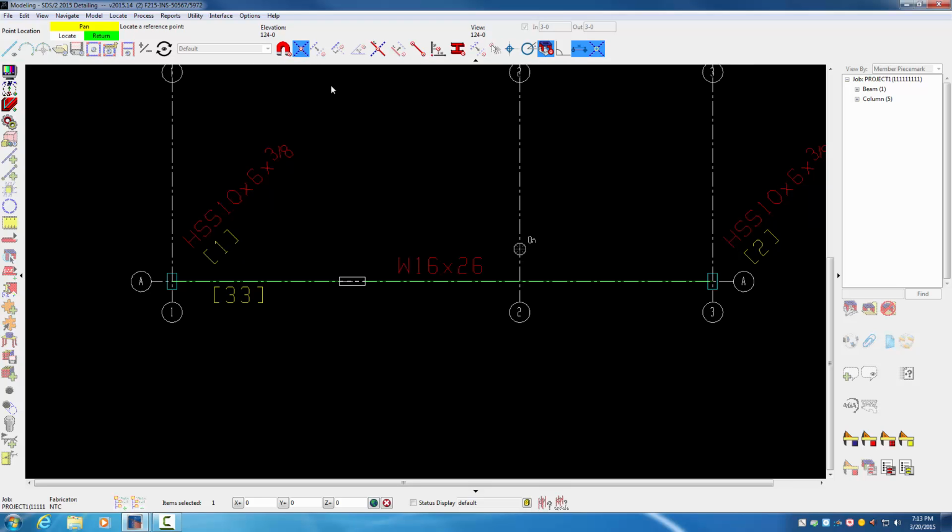So intersection of construction line, you can pick any point you want here. And then for the second point, we can't pick a second point here on the screen because it'll move it whichever direction we're going here. So let's pick your DX, DY offset. So I highlighted that locator. It's still asking me for a second point, so I've got the DXDY location icon selected, so now I'm going to hit my left button to locate using that DXDY, and it brings